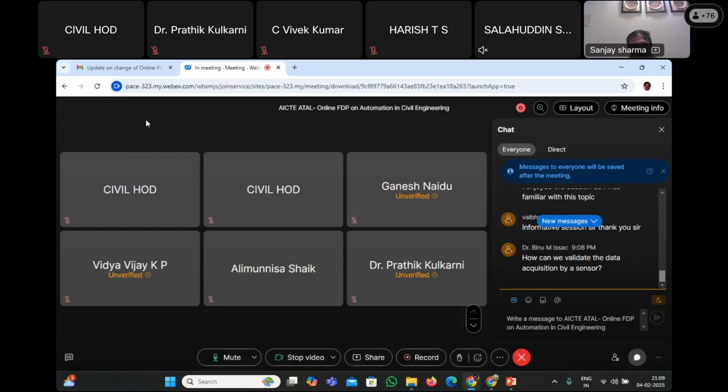Sometimes you need to find out the reinforcement bar also, which I forgot to mention in my presentation. You may be having the ferroscan, or other things. You know the bar diameter, what is the cover to concrete. The carbonation, again, is important. Cover is very important there also. So carbonation, you find out, and cover also, and then sometimes spacing is required.